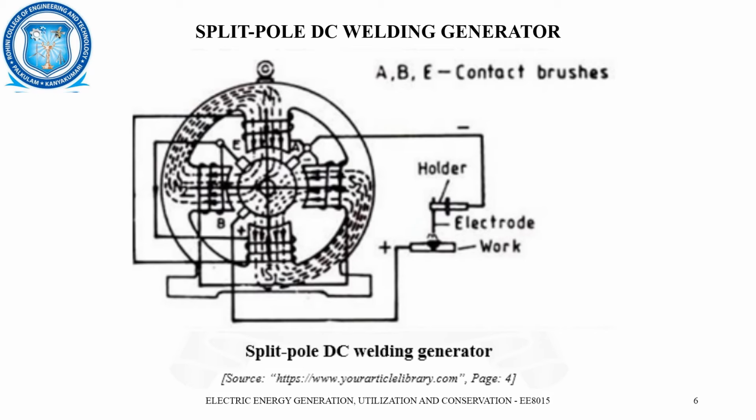The path of the magnetic flux in the armature is shown by the dotted lines. We can see how these dotted lines enter from the north to the south poles. As we see, the magnetic flux in the armature winding moves with the magnetic flux in the poles N1 and S1 and against the magnetic flux in the poles N2 and S2. In other words, the armature magnetic flux tends to build up the magnetic flux in the poles on one side and to kill it on the other side.